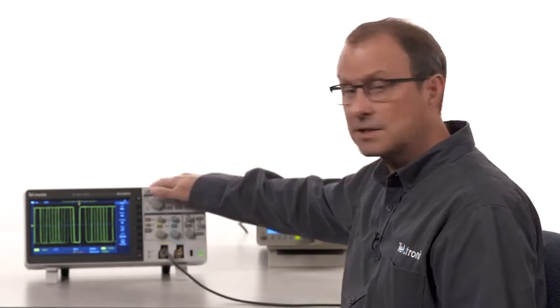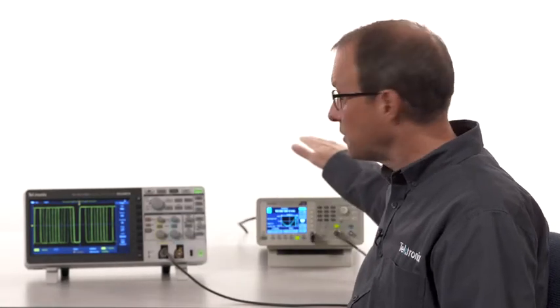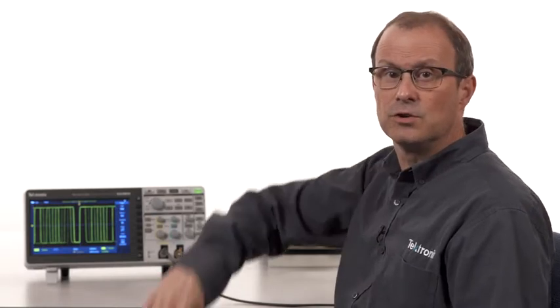In this video, I'm going to use a TBS 2000 series oscilloscope and an arbitrary function generator to show you more trigger techniques. They'll come in handy for capturing digital signals in bursts. I'll use waveforms out of the generator to show you how to use pulse width triggering, show more uses for trigger hold-off, and explain how to use runt pulse triggers.